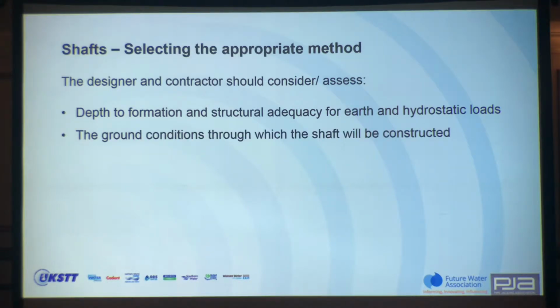The ground conditions, again, that's the theme, I think, of a large part of what we've been talking about. Ground conditions dictate risk. Risk dictates many things, including the success of the scheme. Then there's the need to control groundwater. When you put your shaft in, there are different phases when you're actually constructing the shaft. Groundwater can cause you potential issues. When you get to the base, it can cause you issues, and then when you're trying to get in and out of the shaft itself, it can again cause issues.